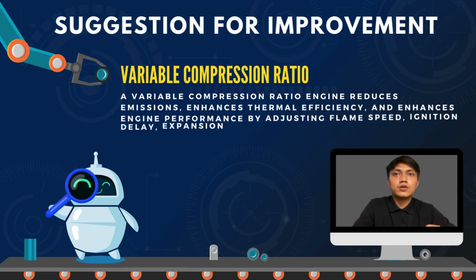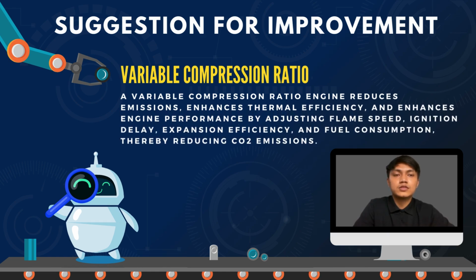Next, we can improve our system by variable compression ratio. A variable compression ratio engine aims to reduce emission, enhance thermal efficiency, and enhance engine performance by adjusting the compression ratio to allow for faster flame speed, shorter ignition delay, and improved brake thermal efficiency. Then reducing fuel consumption and CO2 emission. It improves brake thermal efficiency and produces combustion characteristics with a higher peak cylinder pressure rise.